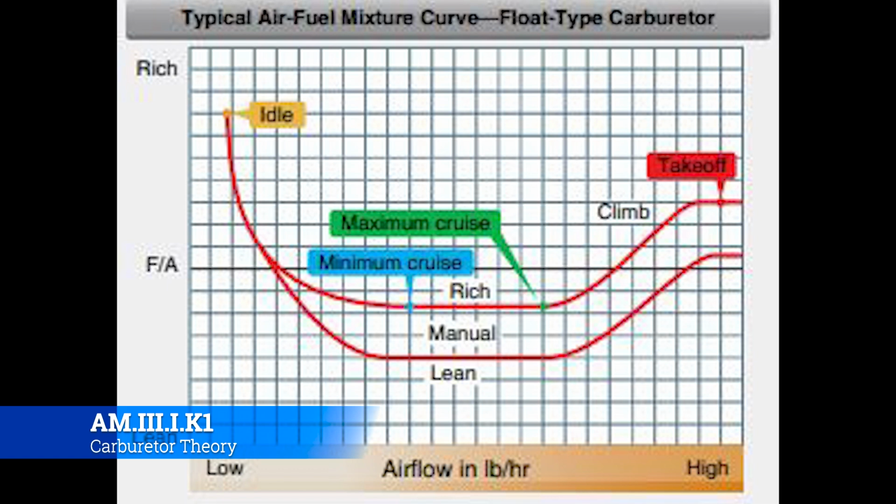That it's rich, you're giving it as much fuel as you can whenever it's just been cranked. Now, typically, this graphic really doesn't do it justice per se, but on the right-hand side where it says takeoff, you're also going to be full rich. I imagine what they're trying to say is that since the airflow has increased while you're taking off and it's running, the extra air is going to help lean that mixture out, and that's true. But for the sake of our purposes, you're going to put it into the full rich position.